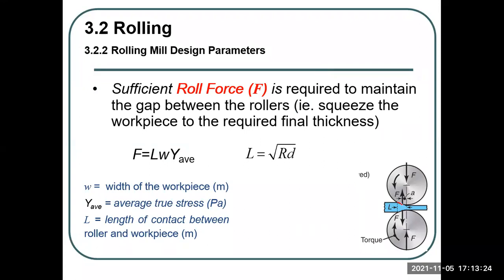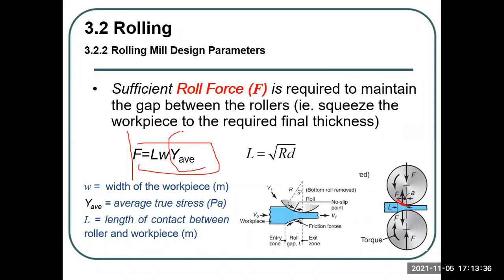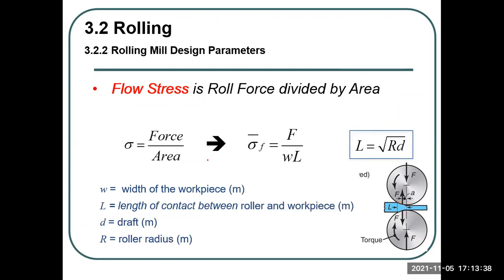L is the length of contact between the roller and the workpiece. All these are the equations. Most of the time the yield strength is given. And for flow stress, another way you can use is force divided by area.